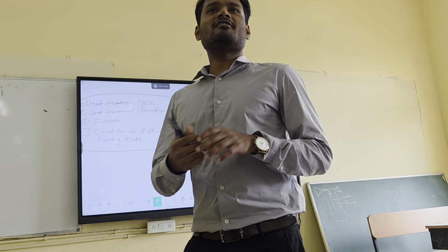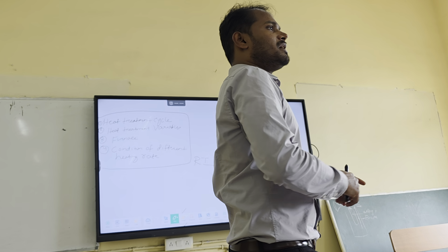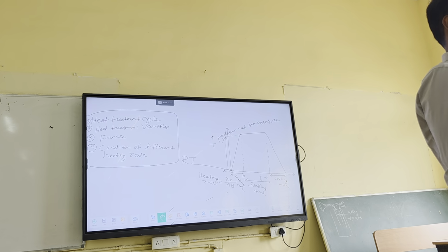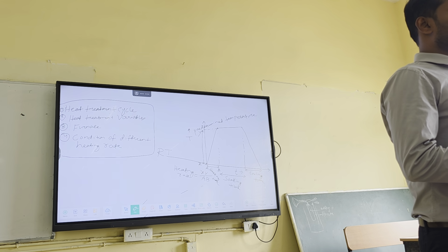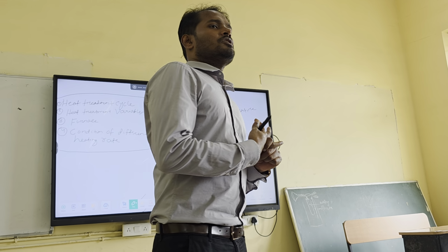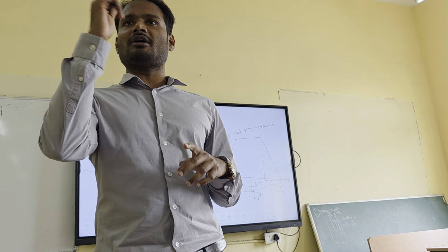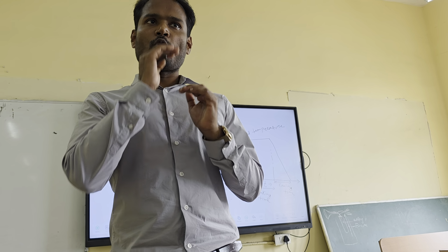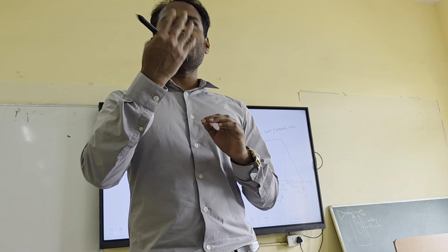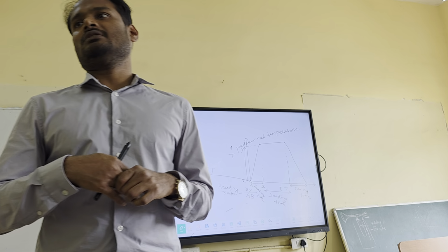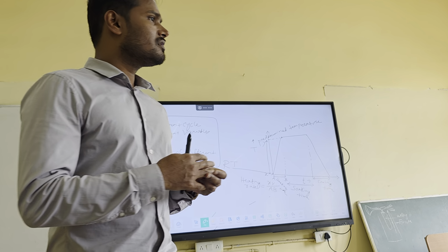But it doesn't mean you will not give a heating rate. You have to give a heating rate, but it will go on like this. Is it okay? So you have to remember, the heating rate will not remain constant throughout the temperature range. At low temperature it will remain the same, but at high temperature it will reduce automatically. Okay? Is it fine?